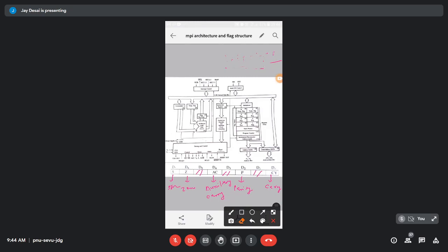Yes, sir. Okay. ચલો. At the end you will get the 8-bit answer. તમને 8-bit answer મળશે. Like this, 1 0 1 1 0 0 1 0. સપોઝ કોઈ આવો આન્સર મળ્યો, 8 બીટ આન્સર. So what you have to do? You have to check the D7 bit, that is the MSB bit, topmost bit, to check whether your answer is positive or negative when you concern about the sign. જ્યારે તમને તમારી સાઇન સાથે મતલબ હશે ત્યારે તમારે શું ચેક કરવું પડશે? તમારો D7 બીટ ચેક કરવો પડશે.